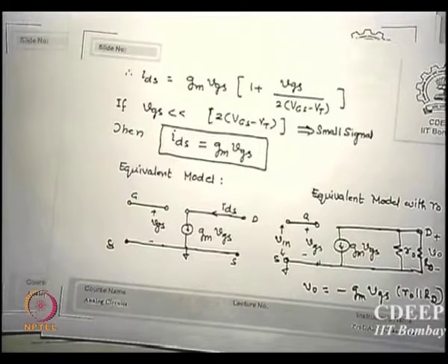At the end of the day in a circuit, the load decides the output voltage, is that clear? But in an integrated circuit, there are no RDs we put, okay. I will show you some at the end of the course what ICs do, okay. We will replace RD by a transistor itself, and if that happens, this will be much larger, typically of the order of R0 itself. So for integrated circuits, gains are GM times R0, but for our normal open circuits with a transistor given to us, the gain will be decided by RD, which is provided externally by us. Is that correct? GM times RD is what gain will actually appear.